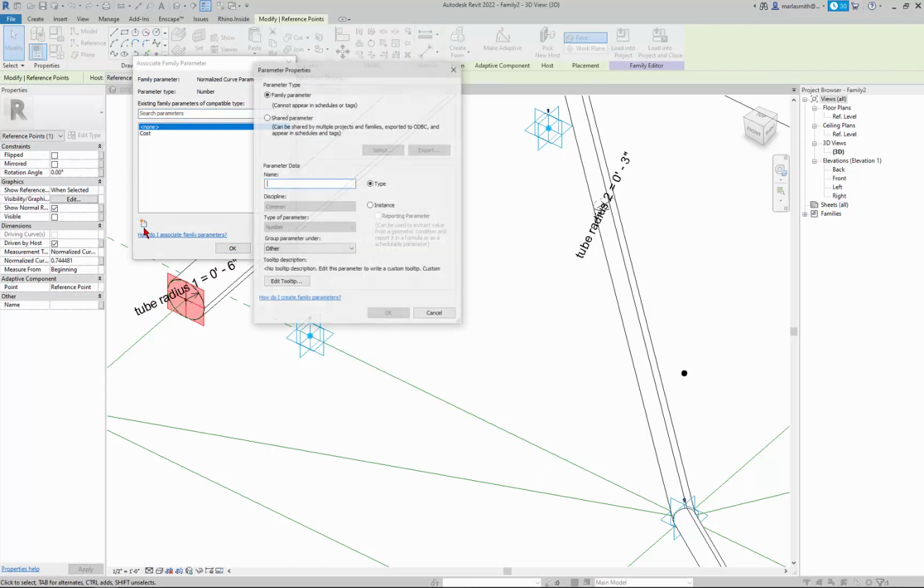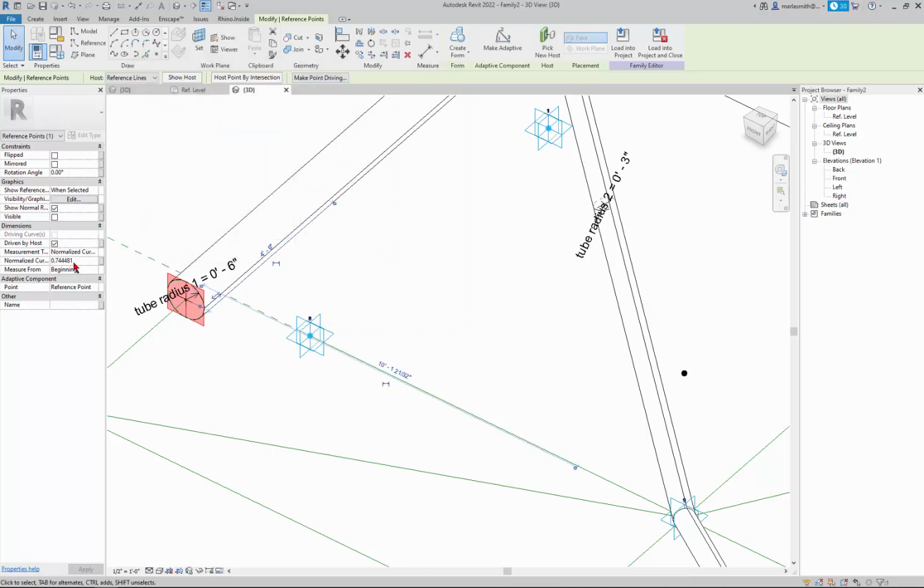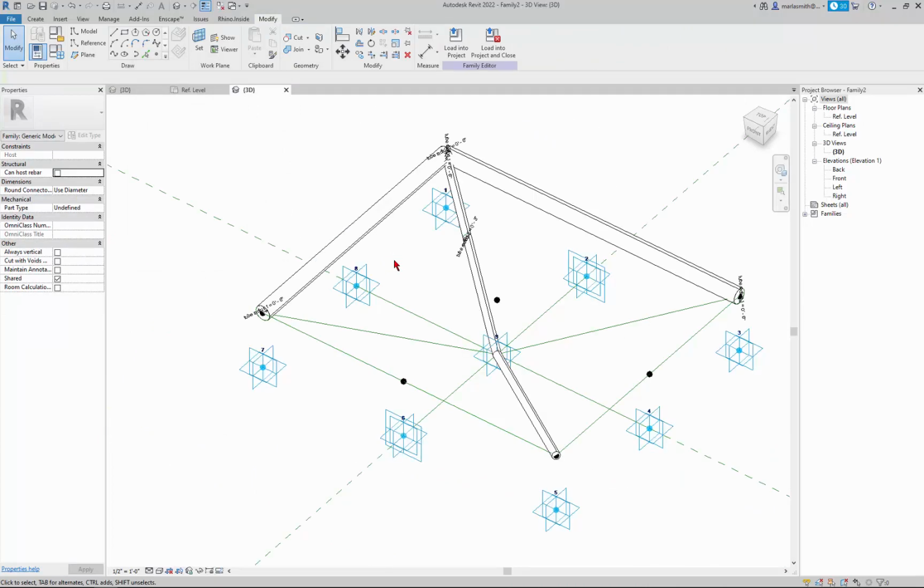If you're familiar with Revit, you can use a nested 3-point adaptive component and just click it in and pass the parameters through. I might talk about that at the end, but for right now, I'm just going to do this all manually.